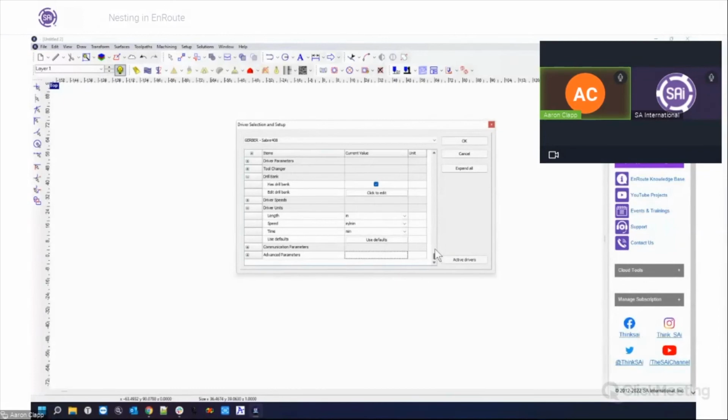The Gerber is a little bit different. It is the only machine that we can communicate to directly. So you need to come in here and set your communication parameters. You'll need to set your port and whatnot. I think we do have a document on how to set these settings that we could probably send you if you ask tech support. They could email it to you.